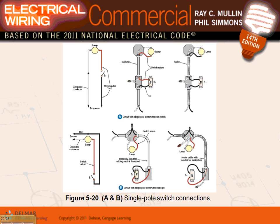Because the reason why here they didn't use the neutral is that code only started requiring it in 2011. If you're wiring with cables, with some exceptions though, you have to bring a neutral. So really re-identifying the neutral becomes not a big deal.